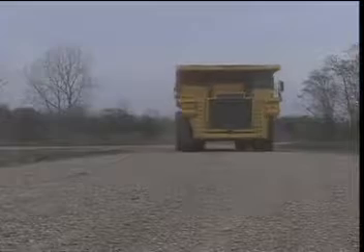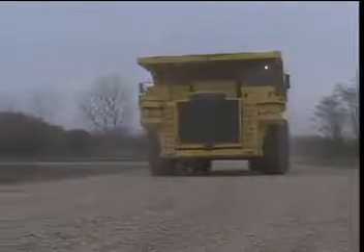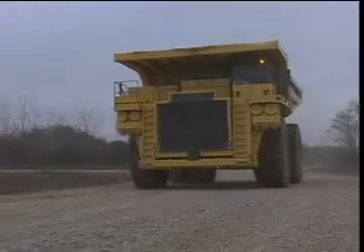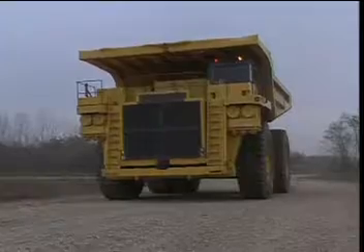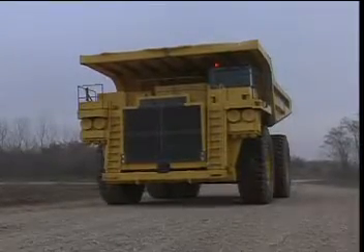An engine is considered hot when the hot shutdown load percent of the engine is above the threshold set in Insight. The hot shutdown load percent is based on the duty cycle load factor, which is determined from engine fueling levels.